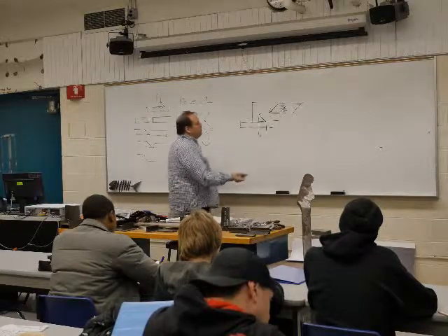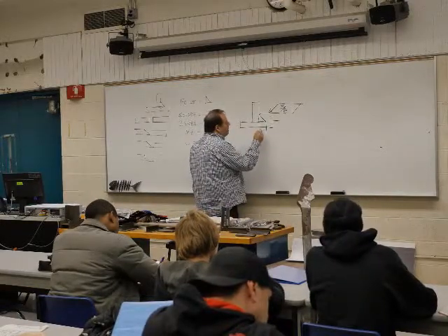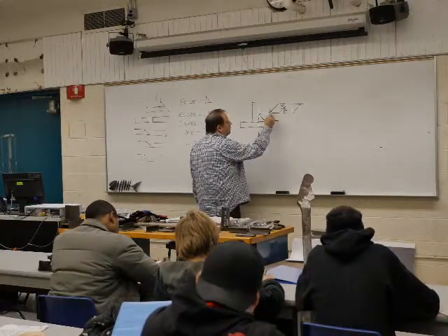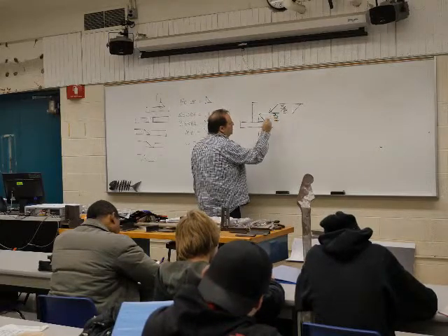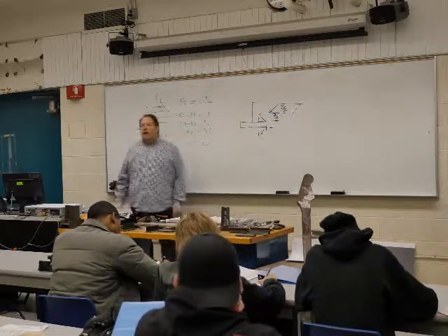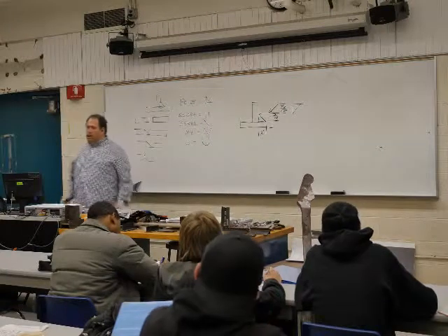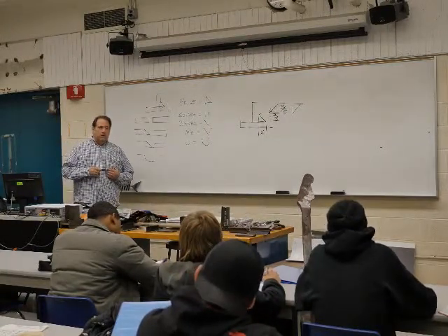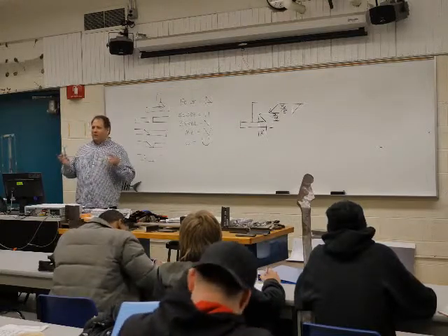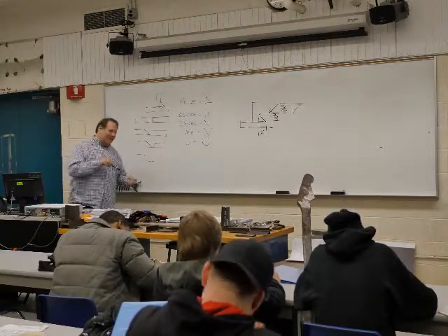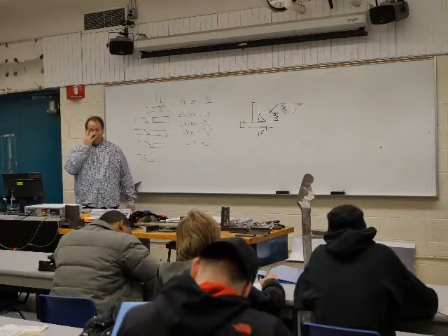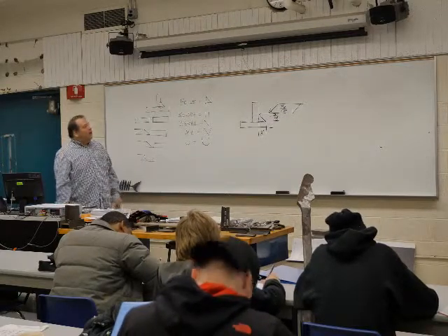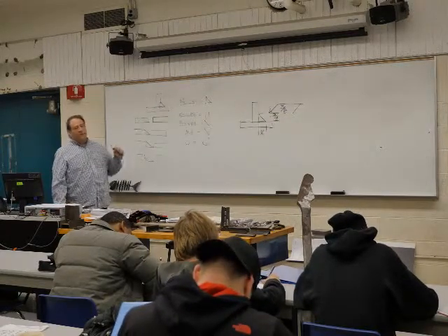If for some reason you screwed it up and say this is going to be a quarter when we measure, but this one comes out 3/8, guess what? That is now a 1/4 inch weld. You have to go with the smallest number. And yes, 1/4 is smaller than 3/8, because a 1/4 is 2/8. You always have to go with that smaller number.